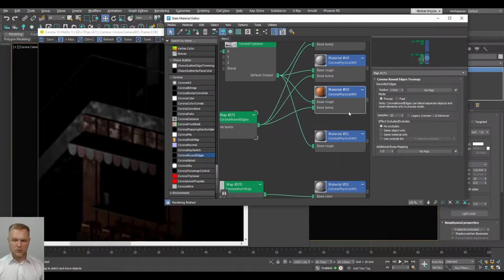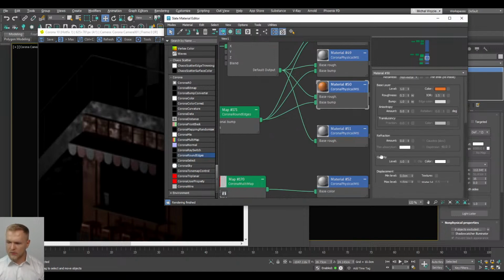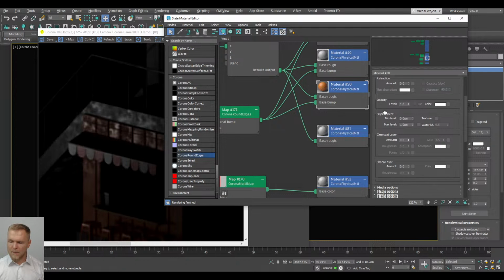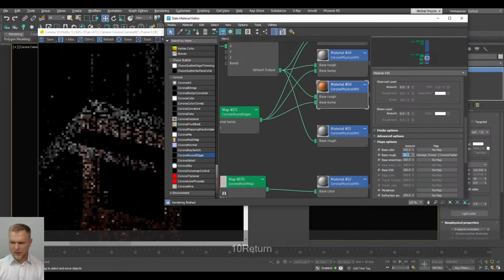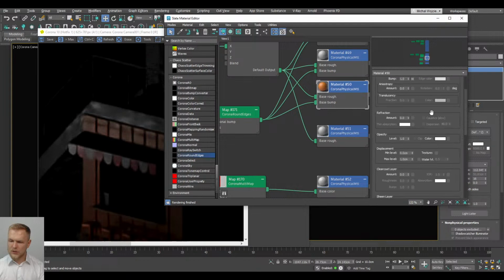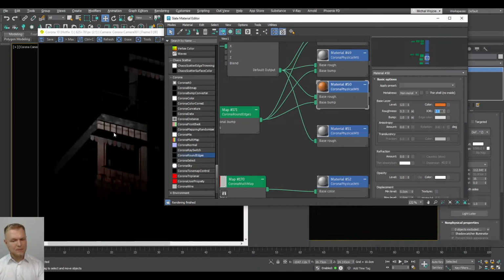So we're actually going to dial this back down, and we're going to go to physical material and change the amount of, how's it called, base roughness. So let's go for 15 in this case, 10. Okay, also maybe increase the reflectability a little bit by going for IOR 2, so it's going to be nice and shiny. It's not metallic shiny, but it's still going to look better.